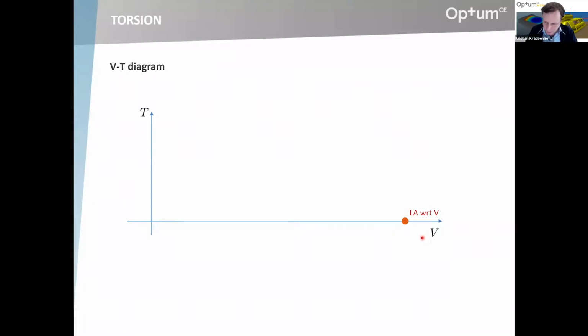So that gives you an upper limit of the vertical load, and you would like the lower limit as well, which in principle is a limit analysis with respect to the vertical force pointing in the opposite direction. That's not really necessary here because it's obvious that it's at the origin here. But if you have a foundation with some finite uplift capacity, that's how you would do it. So you have this range of V, the minimum to the maximum.